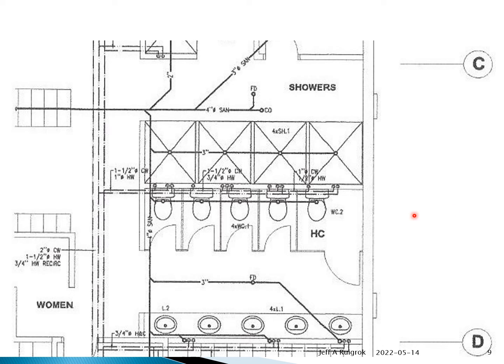This is the piping plan, and it's ridiculous. If you were to actually draw this piping right here, if I turn that and drew it in elevation, it would simply look like this. And again, I said before, you're not allowed to have a T on the horizontal, so that's not even legal. There's no way to even really vent that, and I don't think there's a vent on here. What do I got? 1, 2, 3, 5 toilets. 1, 2, 3, yeah. So you would never do this.